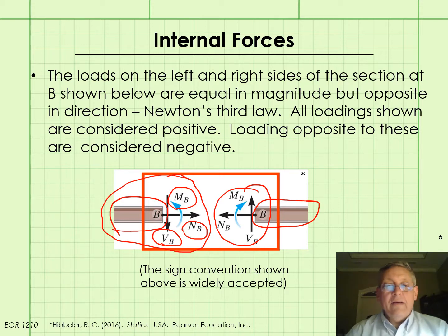So let's look at that a little more in depth. Let's start with the normal force. A normal force that is causing tension is considered positive, okay? So going by that definition, what we're showing here on the free body diagram on the left side of the cut, that's a positive normal force.